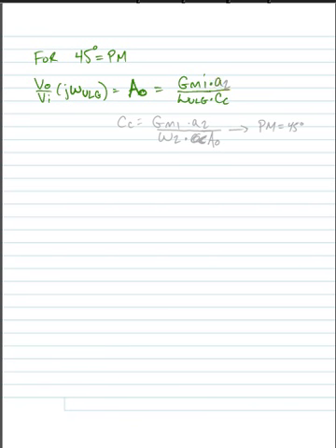Sorry, I left a term out here. There should be an A2 here. Just taking this equation from the prior page of notes. Now, if we solve for the compensation capacitance value, we'd find CC is equal to GM1 times A2. We want the unity loop gain to occur at the second pole in the circuit, so times omega 2 times CC. Or sorry, A0, our closed loop gain. And if we met this condition, we'd have a 45-degree phase margin. Okay, so we will look at one more example before we move on to our two-stage example, or two-stage compensation, using pole splitting.